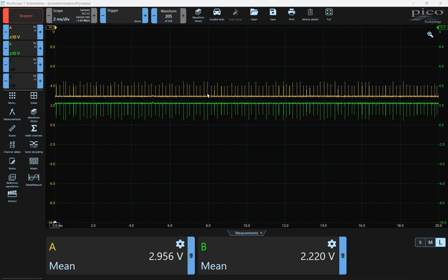If I took it off of the harness, the so-called passive terminator, and only had the active terminator, the 6-wire, in place, the CAN bus, as most of you know, will probably recover. I won't have any issues with it. We don't want to leave it that way, but it should be good enough to function.